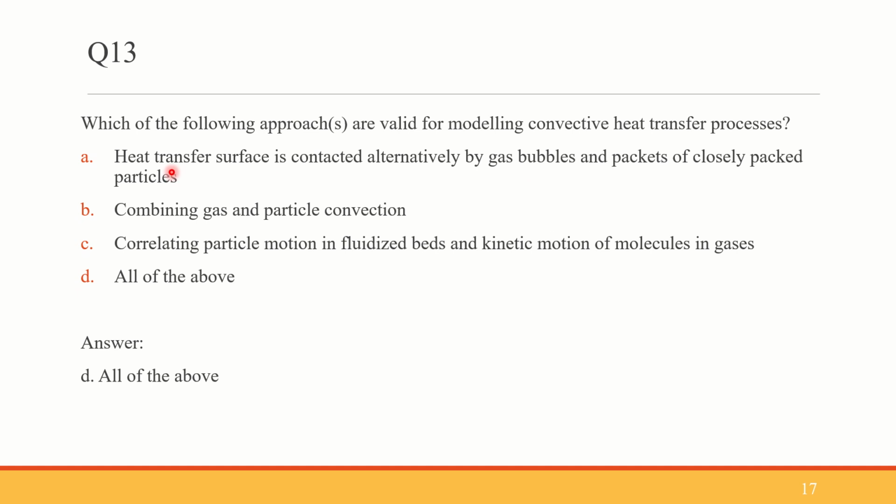So whatever surface we are considering, it is alternatively contacted by the gas bubbles and also by the packets of solid particles. Also combining the gas and particle convection, and then correlating particle motion in fluidized beds and kinetic motion of molecules in gases.